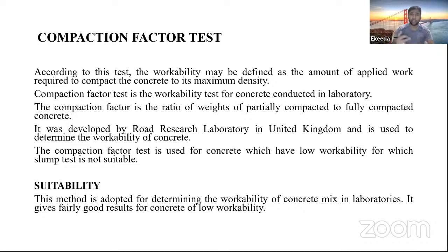To determine the workability of the concrete, we had studied one test whose name is slump cone test, in which we filled the concrete in 3 layers with 25 tamps per layer with the help of a tamping rod. After the third layer filling, we finish the surface with the trowel, and we slowly raise the slump cone apparatus. Then the concrete will fall down, and we measure the height that has fallen down with the help of the tamping rod.